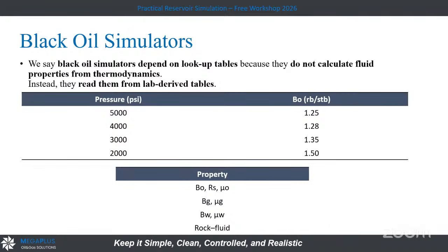In the DLE we produce, so the mass is not constant, and so the difference is that we mimic the reservoir behavior in production. So we will produce this gas, and then we will analyze this gas and see the gas oil ratio and the density of the gas and the compressibility factor of the gas, and we have all the data. We took this data and inserted it in any simulator in a very simple way.